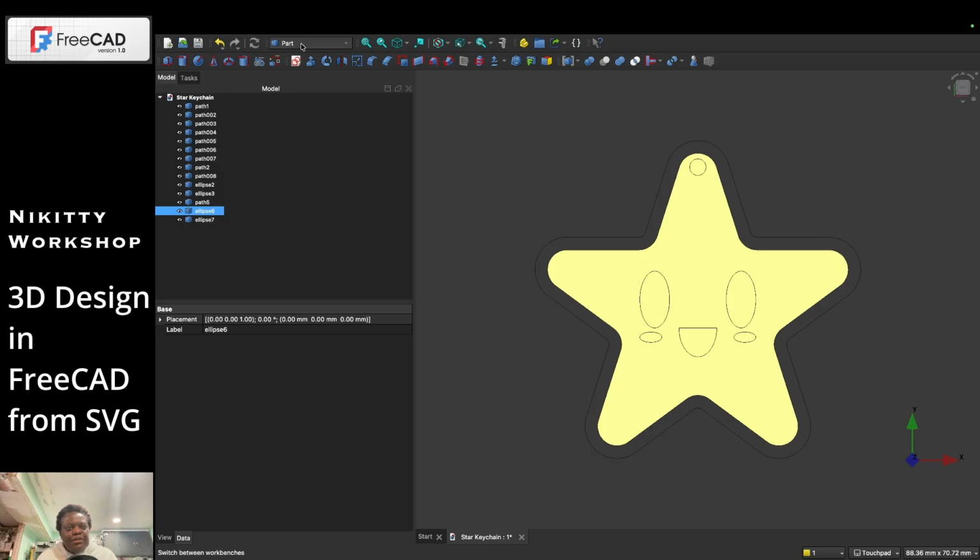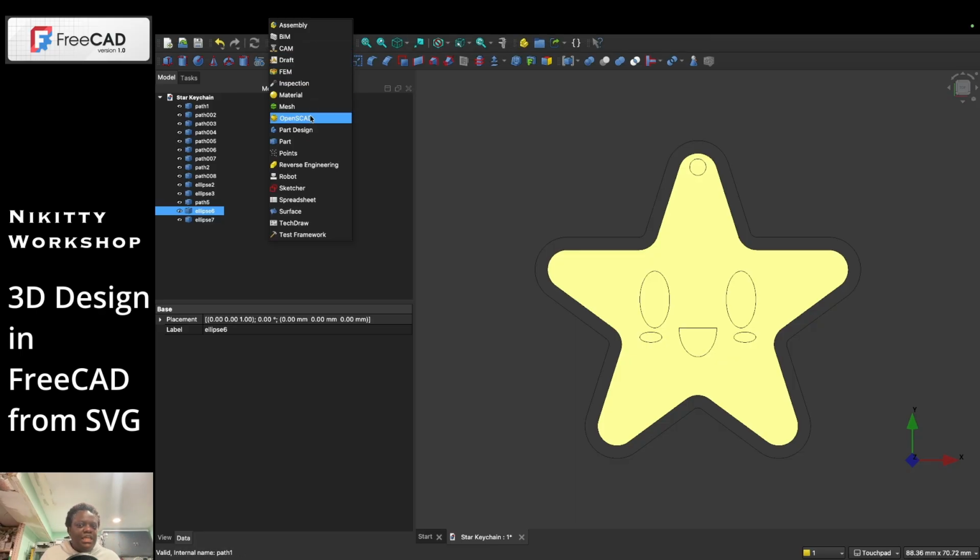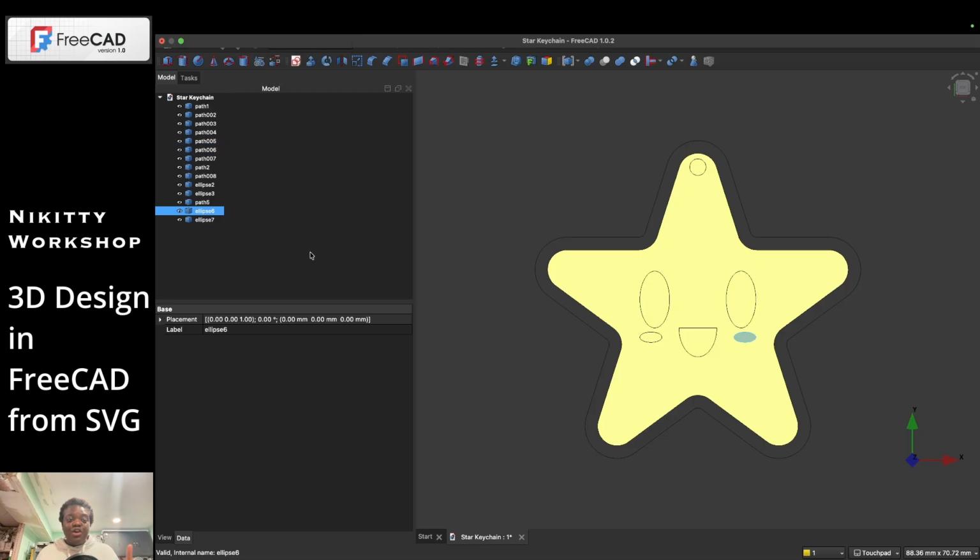The reason why I use part is that, depending on what setting you do, if you do part design, you have to create a body and then do an orientation and pick a side. With the method that I'm showing you, you don't need to do all of that in order to extrude what you need. So I'm trying to do this real simple where I understand it and I can show you guys. So you're gonna make sure you're in part mode. I might get the error that I could show you in draft, which would be good, because then I could show you what to do to bypass it.